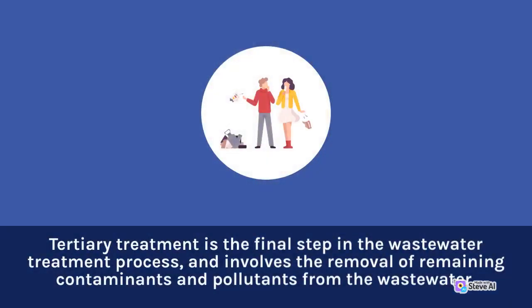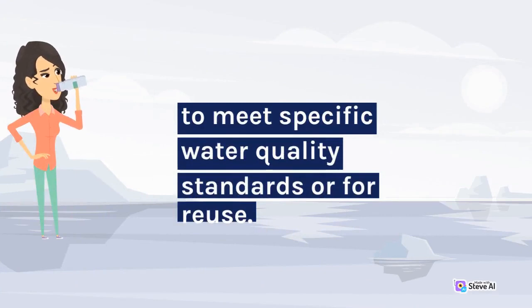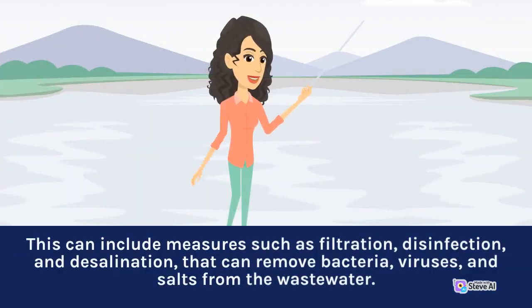Tertiary treatment is the final step in the wastewater treatment process and involves the removal of remaining contaminants and pollutants from the wastewater to meet specific water quality standards or for reuse. This can include measures such as filtration, disinfection, and desalination that can remove bacteria, viruses, and salts from the wastewater.